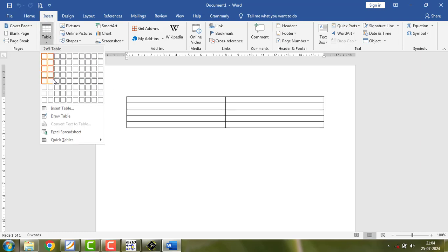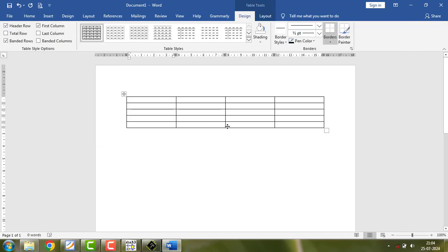We'll try to have these 3-4 cases. Okay. WP equals to WN. What is TPHL? Small t, capital P, HL, high to low. TPLH, low to high. TPD is, you can take average of this, or there are other ways to calculate. We are very much interested in this now.